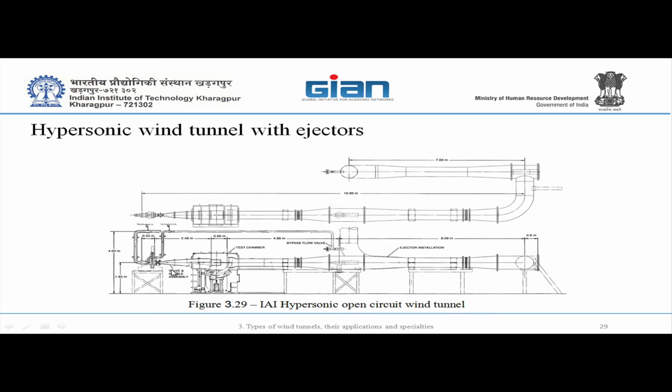Valve. This is the main valve. There is only one valve, and it is driven by the main compressor. We use here the driving of the compressor, which is 30 atmosphere or so. This pipe is coming from the heater. Such a wind tunnel has a lot of side systems. It has a heater, it has filters, it has a dryer, whatever you need.